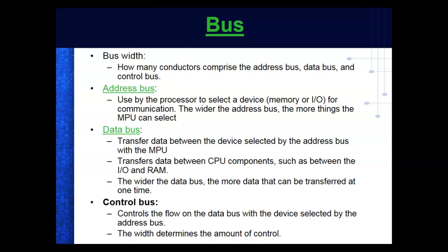So, what determines how many letters the mail person can put inside a mailbox? The size of the mailbox, right? So the size of the mailbox would be similar to the data bus. So they're defining the data bus. So the data bus says, okay, this is how much data I can handle in one cycle. One cycle. So when they say it's a 64-bit processor, that means there's 64 pins on that processor dedicated to the data bus. So they're not defining the address bus.